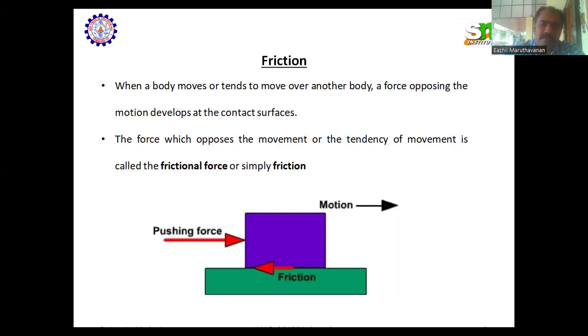The major cause of friction between metals appears to be the force of attraction known as adhesion between the contact regions of the surfaces, which are always microscopically irregular. Friction arises from the shearing of these joints, which might be a welded joint or any kind of joint, and from the action of irregularities of the harder surface flowing across the softer surface.